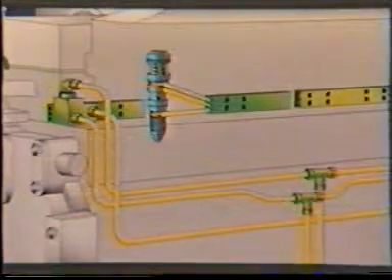Drillings in the cylinder head intersect with the fuel manifold. Timing fuel and rail fuel pass through the cylinder head to the injector. Drain fuel from the injectors passes through the cylinder head to the fuel manifold. We will talk about the QSK-19 fuel system injectors later in the program. In applications where the fuel supply tank is higher than the engine, a check valve prevents drain fuel from flowing back into the system when the engine is not in operation.